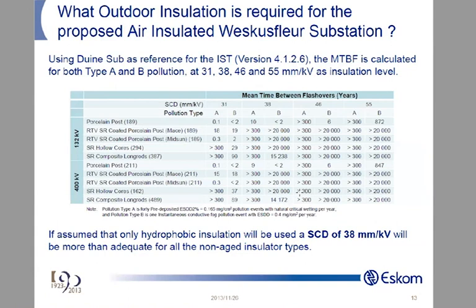What I would do, for instance, is have a little in-service test station online. I build them, it's easy. You can use an existing tower, put up 9 insulators on it, coated with different coatings from different suppliers, and you evaluate them, and then you must live with the fact that 1 or 2 of them are not going to make it.